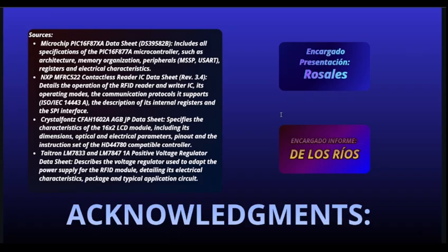Crystalfontz CFAH1602A-HB datasheet specifies the characteristics of the 16 by 2 LCD module, including its dimensions, optical and electrical parameters, pinout, and the instruction set of the HD44780-compatible controller.